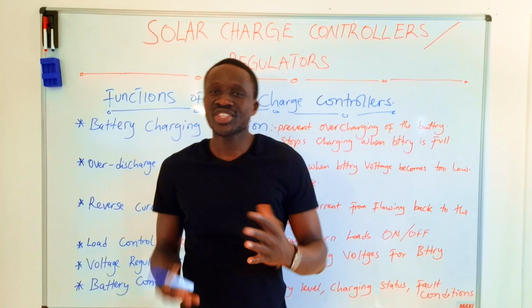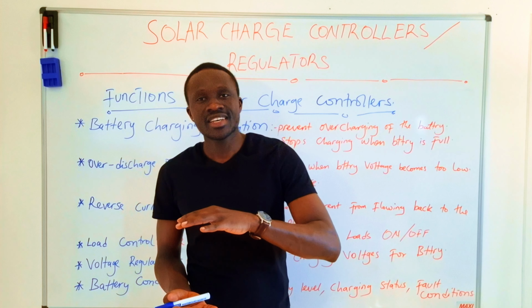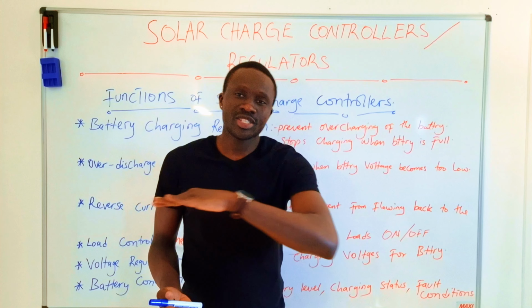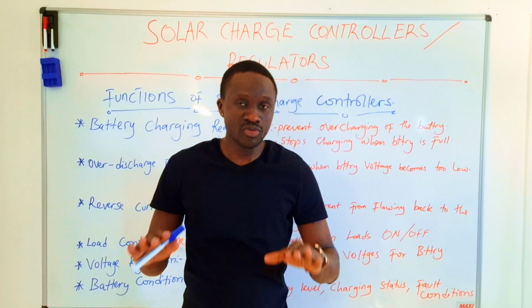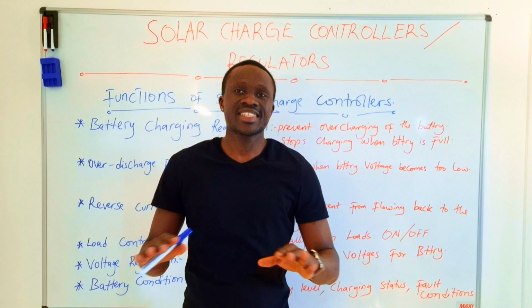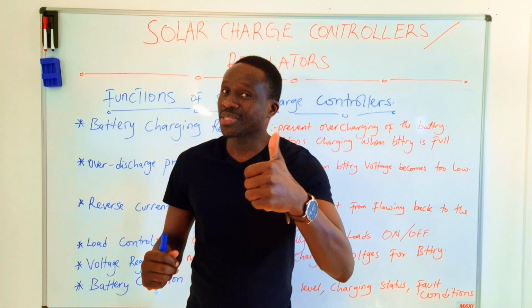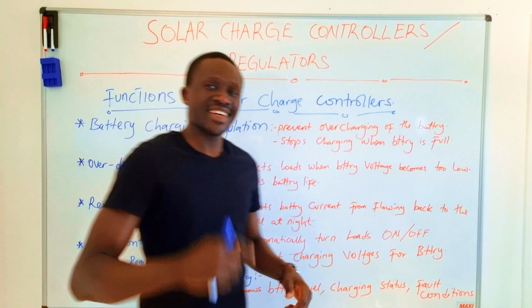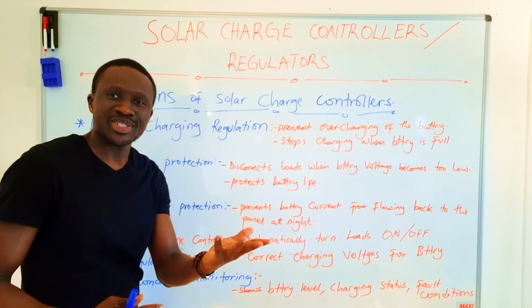If you control charging and discharge, when the battery is discharged to the limit, then it disconnects so that the battery is not over discharged. And the life of the battery will be at par with the customer. As a technician, never install without a regulator because it has good functions.